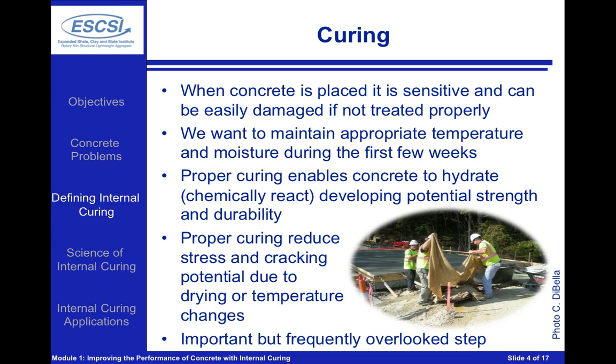Proper curing is important because it's going to enable concrete to hydrate. It's essentially going to allow the reaction to occur between water and cement, and that reaction that occurs is important because it's going to allow the concrete to develop strength. It's going to allow the concrete to become more durable, and by reacting the cement with the water, we're going to fill in the porosity of the overall system.